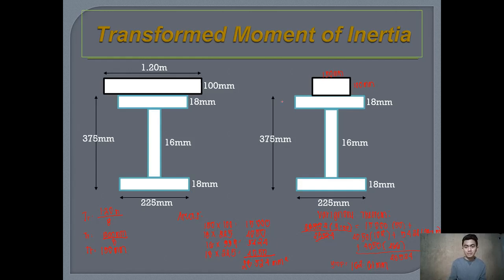So from the top, this is now 118, and then approximately our neutral axis, basing it from what we have computed, will be located at this part now. So I have here now our neutral axis, wherein from the top, the distance now is equal to, here, y top is equal to 162.61 mm.